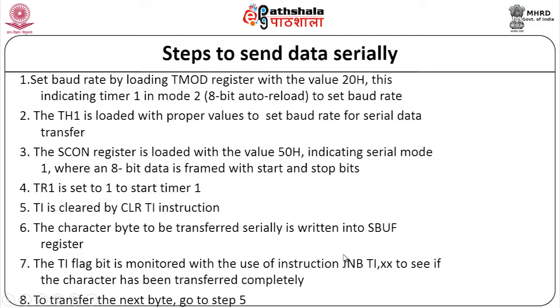That means the transmitter is sending the data from the SBUF. Once it is completely transferred, the system sets this particular TI flag. So this has to be monitored continuously until you get TI equal to 1. That means we will be going to step 5 again and again.